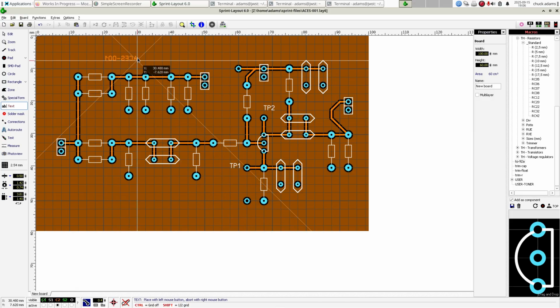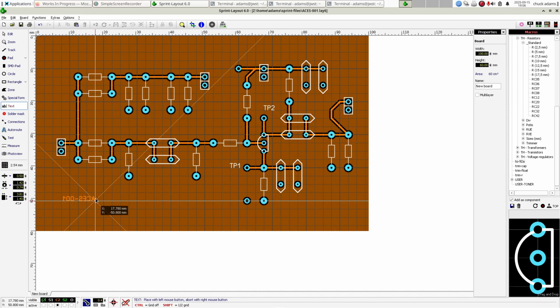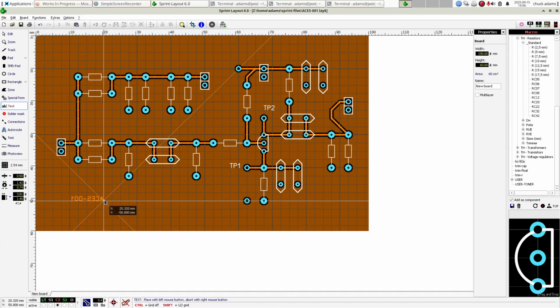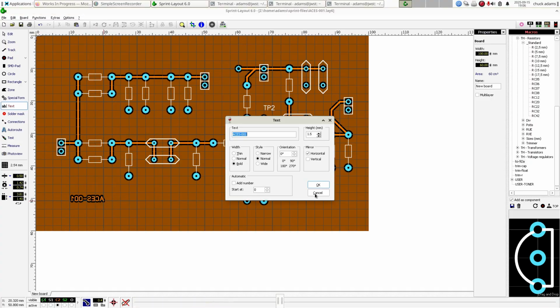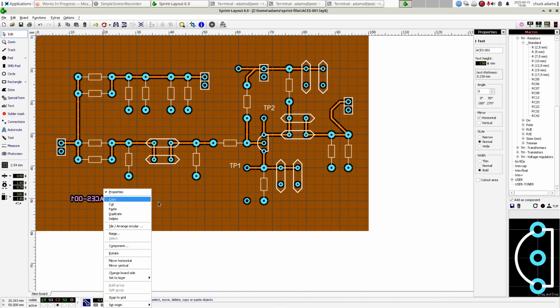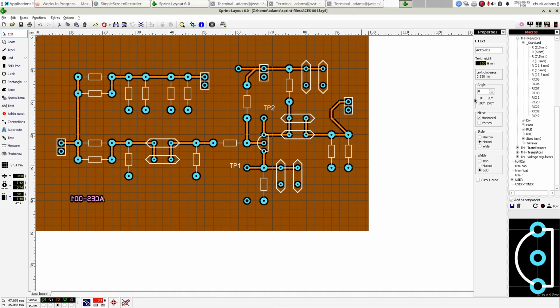Let's put it somewhere. Where do you want it? You want it down here? Let's put it right there, and then I'll right click. Whoops, I didn't right click. I killed it. I'm sorry. Okay, do a left click, and now when I etch the board, you'll have blank areas, and maybe that's not big enough. Well, I can click on this. Whoops, let me click on this. I go over here and change the height. Let's make it 2 millimeters. Okay, makes it large.